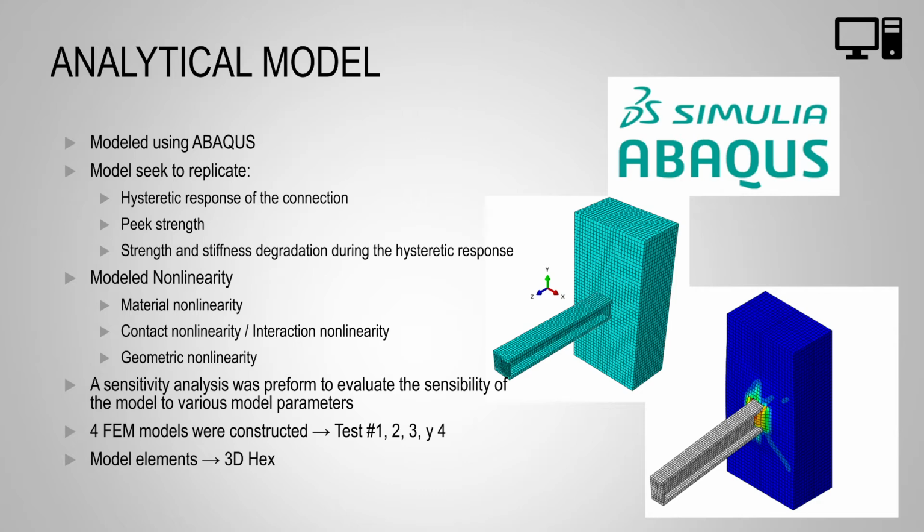In the model, solid continuous hexahedral elements were used. These are called C3D8R elements in ABAQUS. These correspond to 8-node elements with reduced integration and hourglass control. The order of integration was selected as linear. The element type and the geometric order of the elements respond to a balance between precision and analysis time.